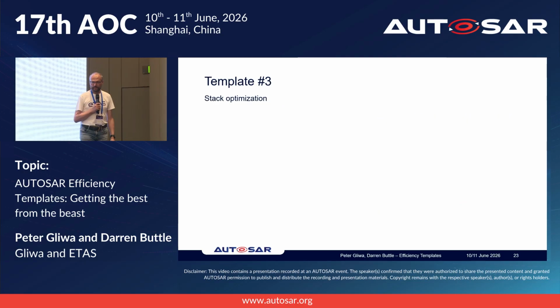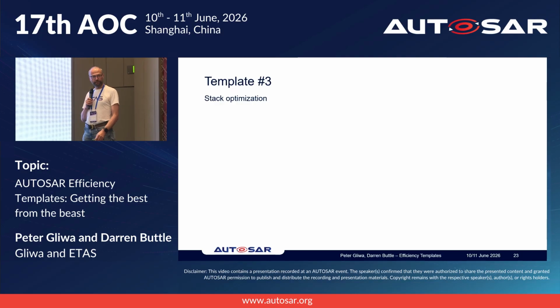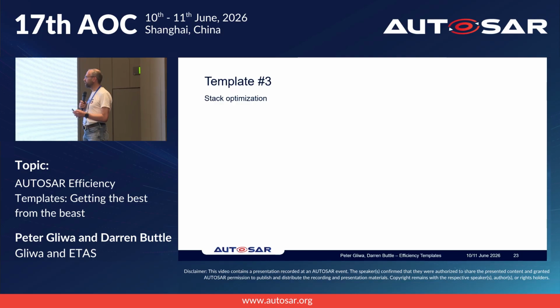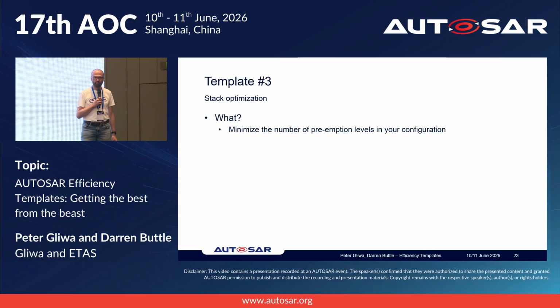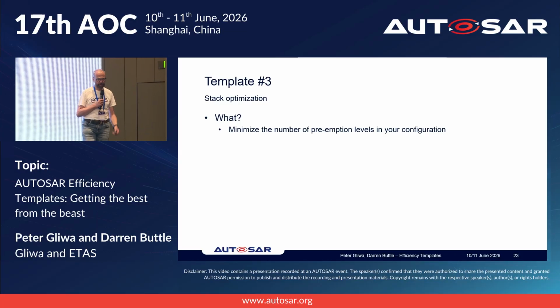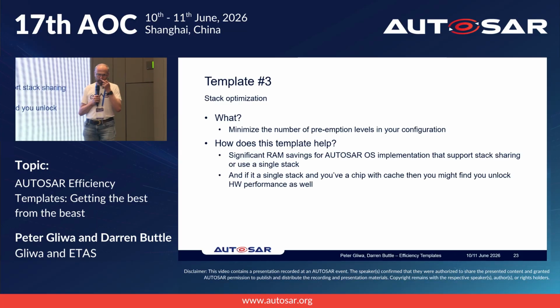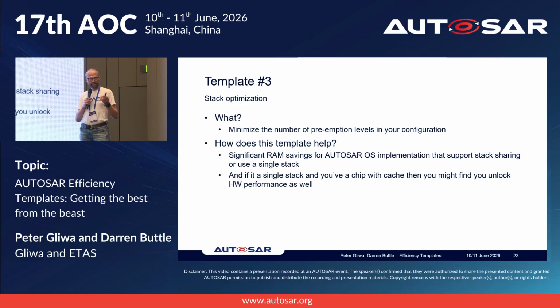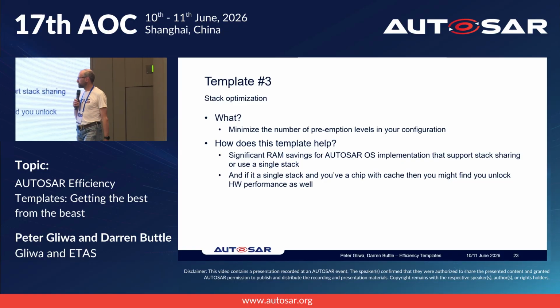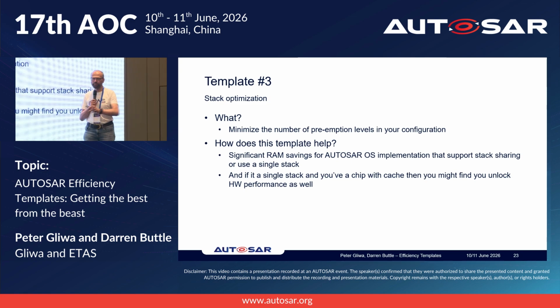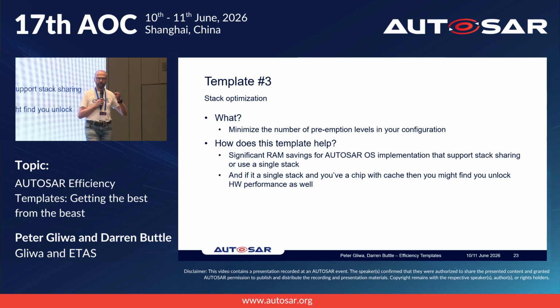So template 3, stack optimization. This is a friend of template 1, actually, but we'll go into this in a bit more detail. It's minimizing the number of preemption levels in your configuration. Okay. So how does this help? Again, significant RAM savings here, particularly for AutoSAR-OS implementations that support some kind of stack sharing or use a single